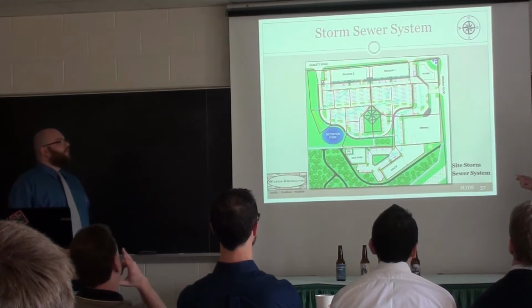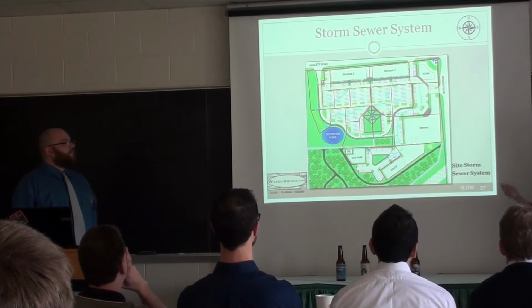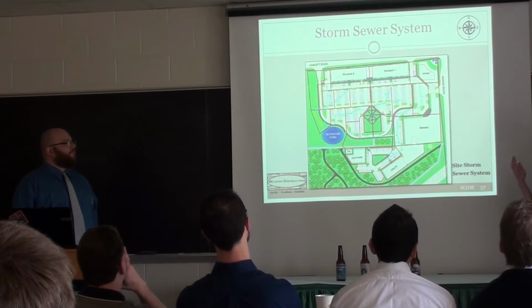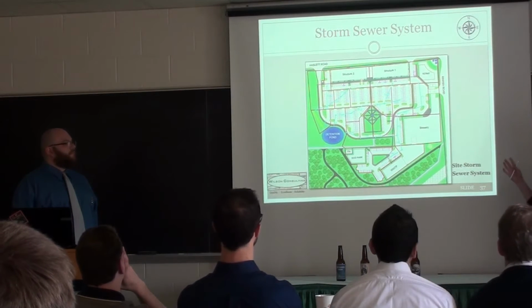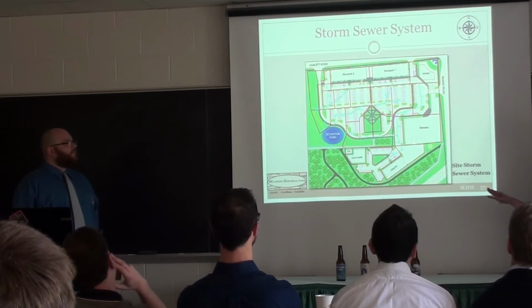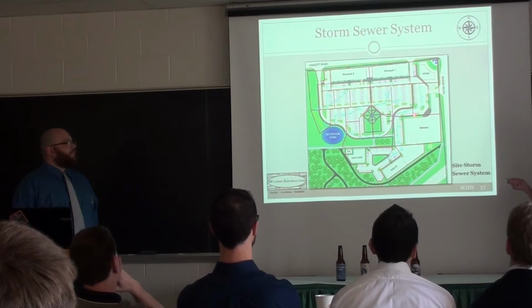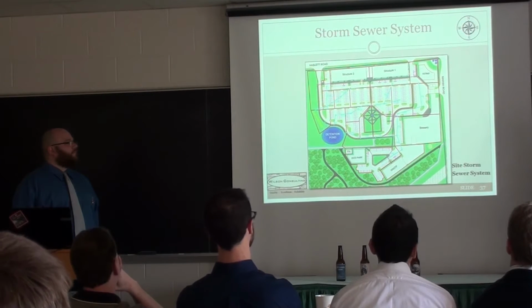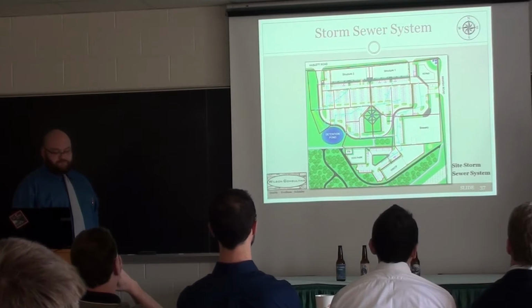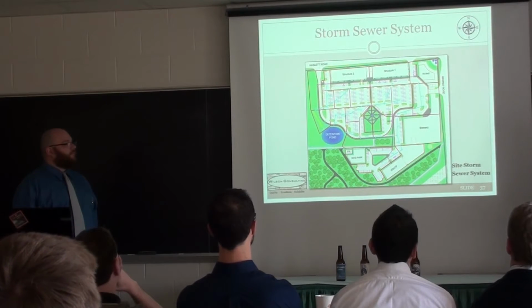You can see that the red boxes, those are just conceptual subcatchments, so that the rainfall that flows into these areas will then be routed via the grading that's selected for the site to the inlets of the sewer system network. So we have 3 networks on site. There's one along the eastern and southern side going to the detention basin, one through the center, and then this system over here in the northwest corner will be feeding over to the swale that we have. So the detention basin will have 3 inlets and 1 outlet, which I will be discussing later.